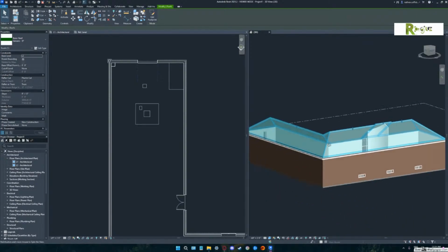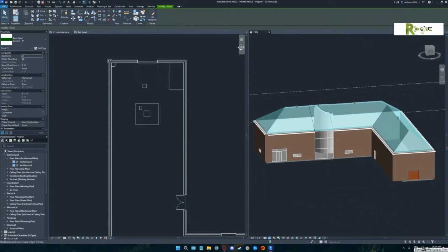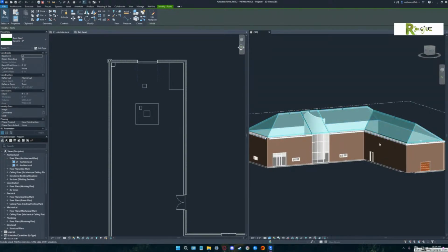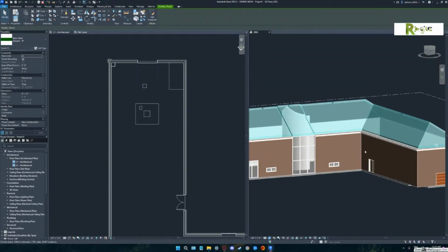Now, what you would have probably wanted to do is with that purple shape, and we can still do it, is if you click on that and say edit profile. This one right here? Nope, the purple shape. Do the double click. Edit footprint. I'm sorry, edit footprint. Up top, up in the menu box. Oh, I got there. You go.